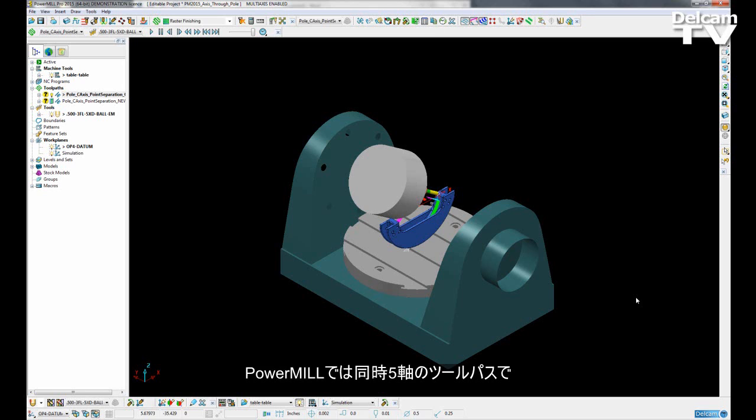In parallel, when machining a continuous 5-axis toolpath, sometimes we encounter problems when the tool axis passes close to the machine tool pole, which is typically the vertical axis, or Z, where the A or B axis is controlling the elevation and the C axis controlling the azimuth angle. As we approach the pole, the tool axis may have to go through a very rapid change between points as it passes through or close to the pole.